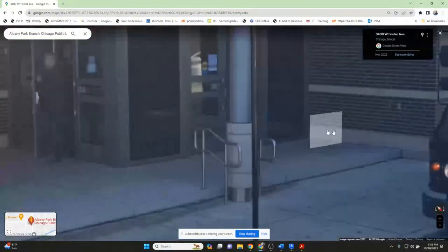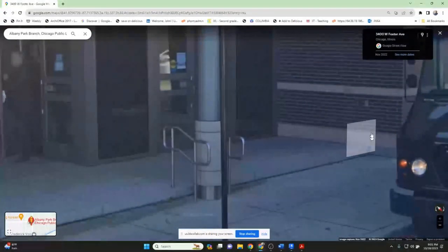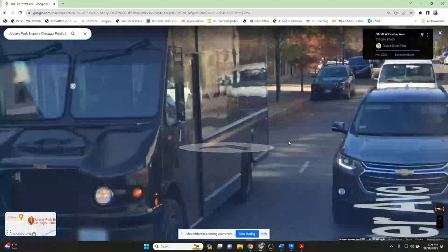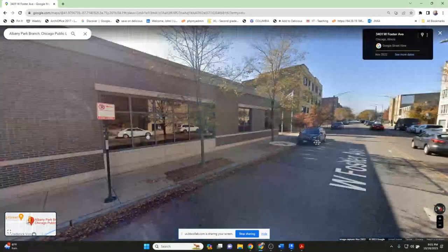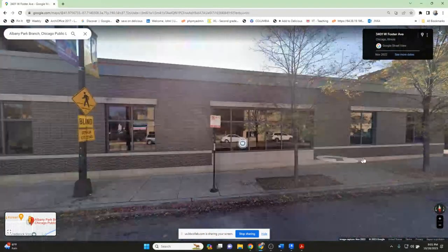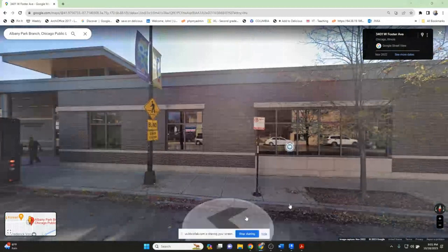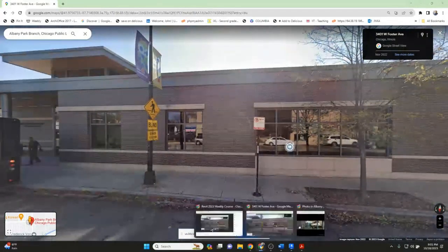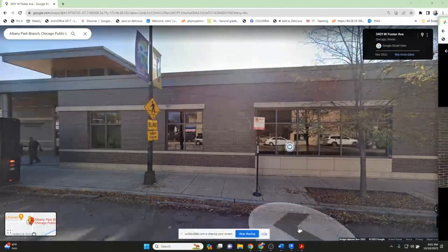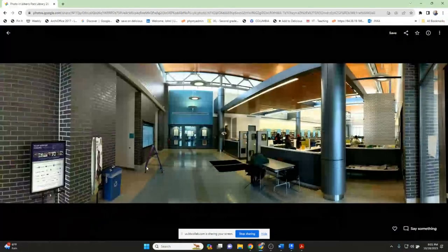That could be done with a split face, or you can add that little concrete base detail to the wall type, because it doesn't stop and start. It's continuous everywhere. It runs the entire length of the building. It's inside and outside the building. I'm assuming I can see it from inside the building photos. So because here it's inside the building right there, that can be saved as part of the wall. You probably want to add that to part of the wall.